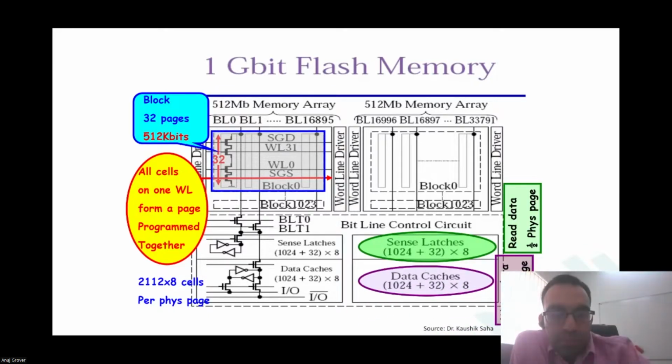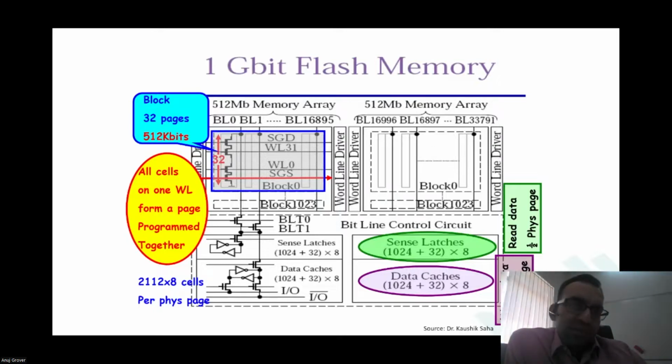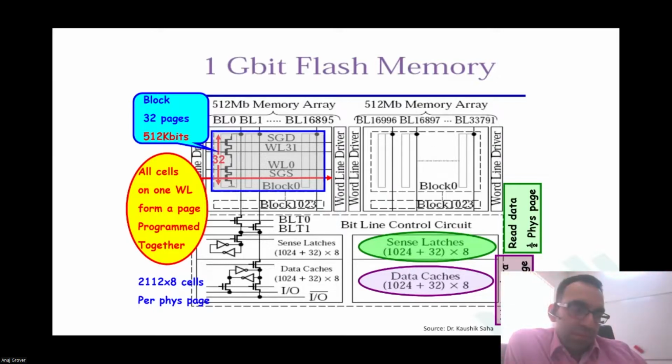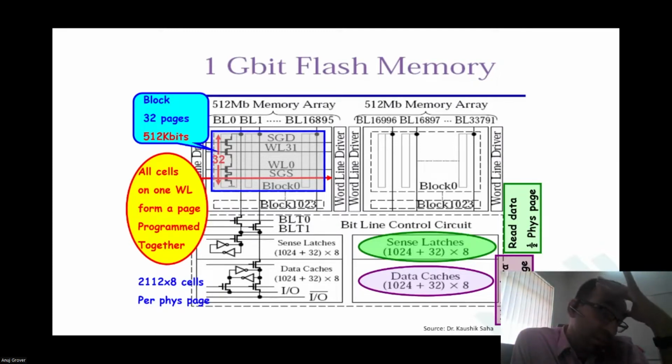Sir, would that also mean a lesser number of bits will be required for error correction? Why would you say that? Sir, what does the number of bits in error correction depend on? Is that the size of the word? Yes, the length of the word. For example, if the word is 32 bits wide, you will need 5 error correction bits for a SECDED code. So it's like parity generation, something like that. Parity is always 1 bit. But error correction code generation depends on how many bits your data has.